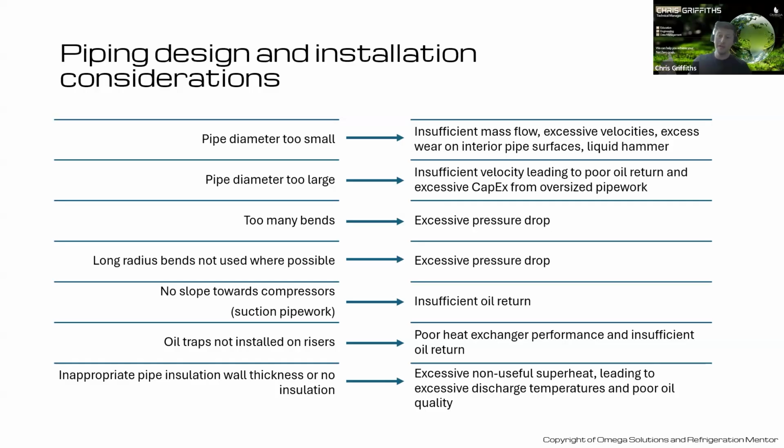When it comes up to a valve, there's a lot of energy inside that fluid. If you try and shut the velocity down, that energy's got to go somewhere. It ends up forcing its way into the walls of the pipework, which can shake the pipes. If it's against bends, long radius elbows, short radius elbows, eventually over time it will fracture those and it will leak out the system.